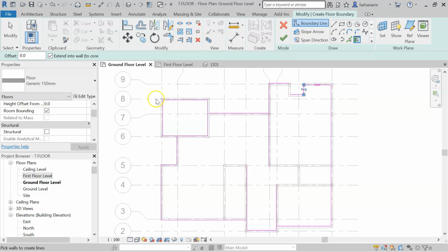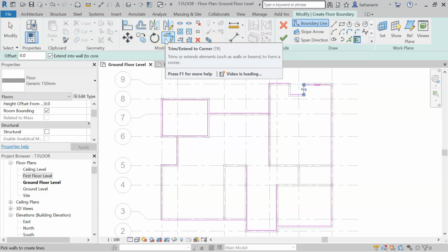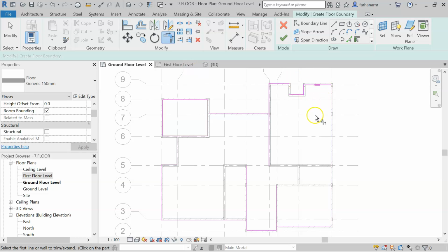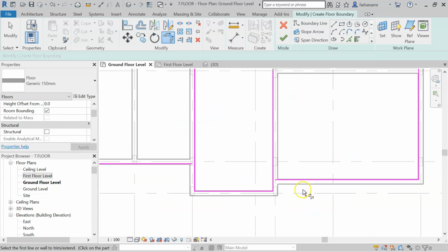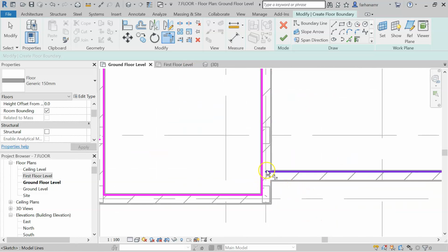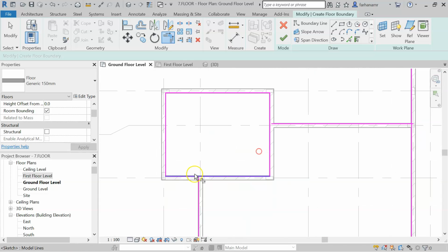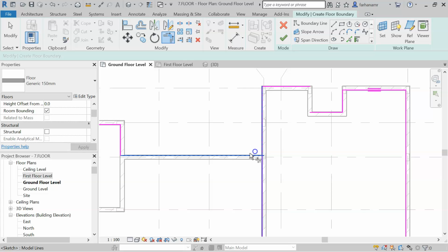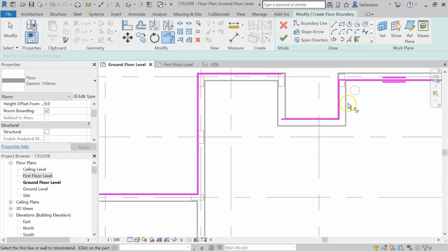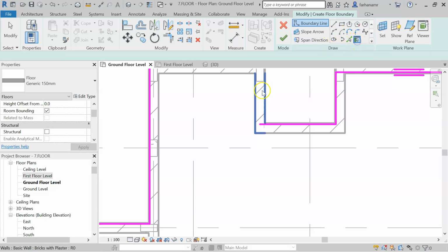After picking all walls, what we can do is trim the corners so that all these lines will be in one loop. So for here, there's an empty gap between lines. We also cannot have overlapping lines. We need to draw another line here.